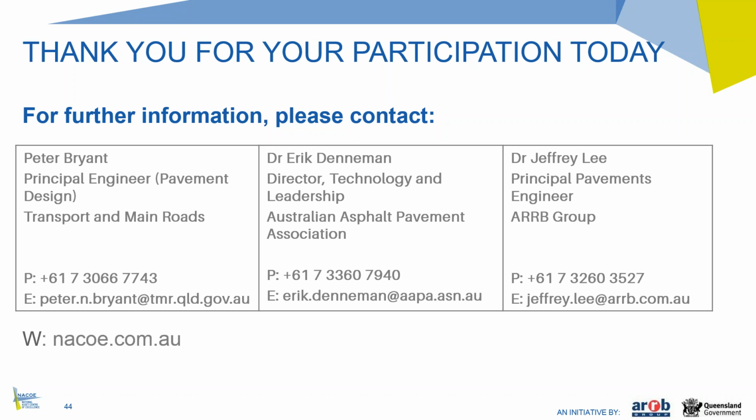Asphalt increases in stiffness over time, so the modulus should go up, as long as there's no damage done. The other side of that coin is that as the temperature goes up, we would actually expect the fatigue performance of the material to improve. So I wouldn't be too concerned about that if we're really looking at only the technical aspects of it. I'm very concerned about global warming, but not for our asphalt items.